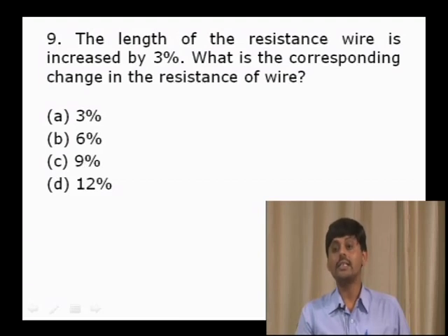That is called stretching of the wire. Here the length is increased by 3%. Say for example, if x% of the length is increased, its new resistance increases by 2x%. By taking the help of that concept, we can easily solve this question.